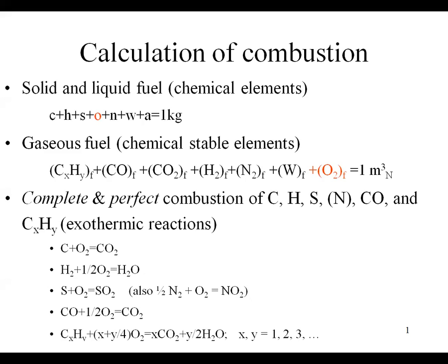We are speaking about a perfect and complete combustion. Complete means everything that can be used in the combustion is used. You don't have any losses. Perfect combustion means that in the flue gases, you don't find any more elements that could be used in combustion, such as CO, for example. So if the combustion is not perfect, for sure, in the flue gases, you will find CO in the case of solid and liquid fuel, or you will find hydrocarbons, for example, in the case of gaseous fuels.